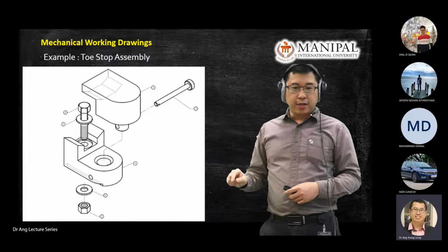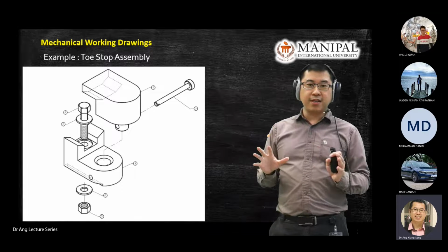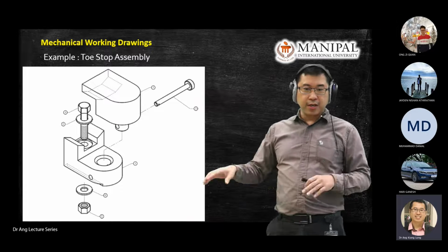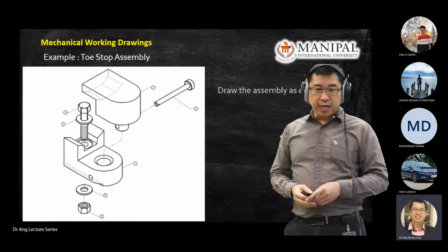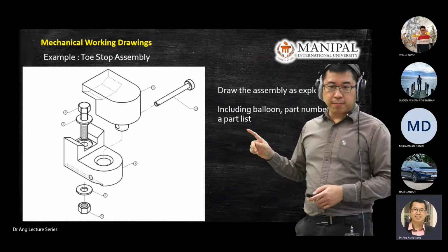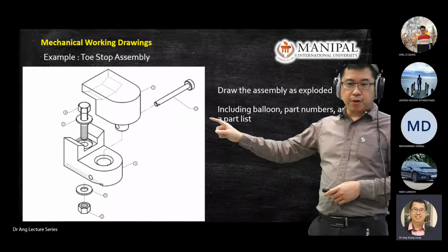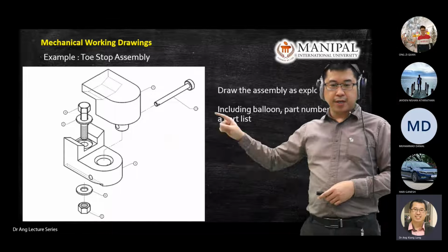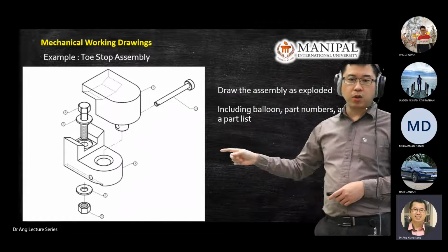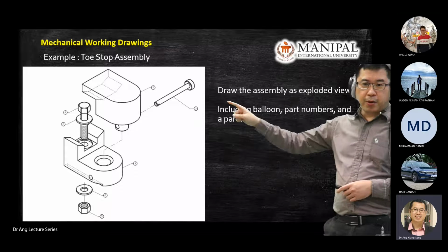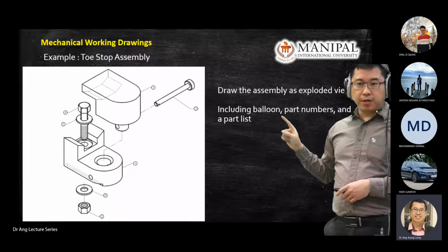After you come up with the parts, I think you already showed me the hand sketching, which is good. You only need to convert the parts into a 3D model and then generate the BOM. Then, in assembly, you put all the parts together in one window. You import the parts into one window, and then you do labeling with balloons.